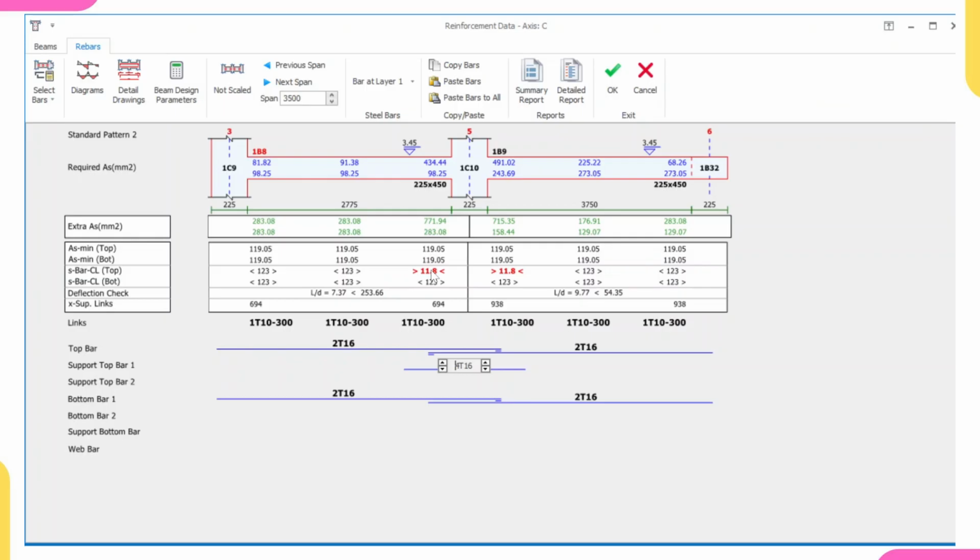Yes, because the size of our coarse aggregate is 3/4. That means if that's our gravel, our coarse aggregate is our gravel. If the size is 3/4 and that 3/4 is 20 millimeter, so make sure, because this is the spacing between your rebars. Okay, let's come over to detailed drawing.